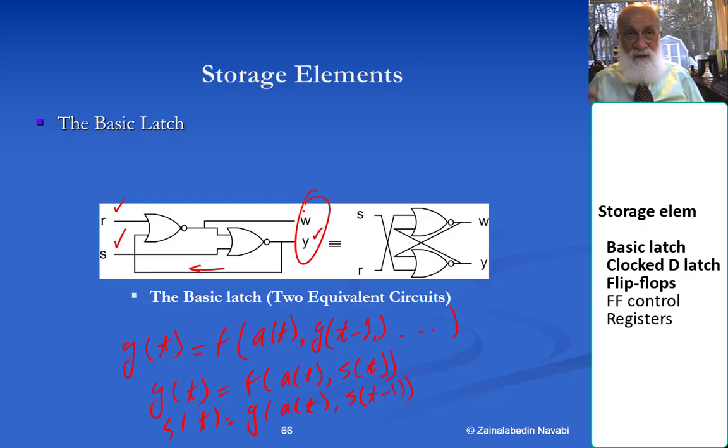The fewer feedbacks, like in my circuit, I only have one feedback. It only remembers one thing from the past, either a 0 or a 1, okay, or maybe two things. But there is one line, since everything is binary, so it remembers either a 0 here or a 1 here. So that's the basic element and the basic concept behind memory elements.